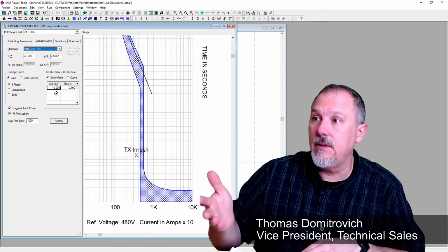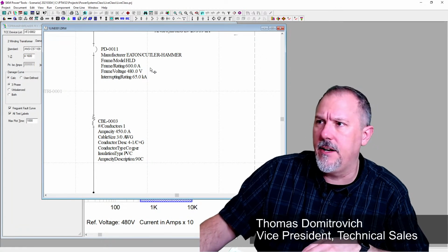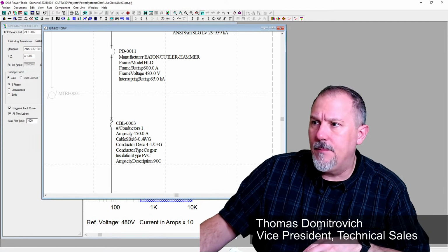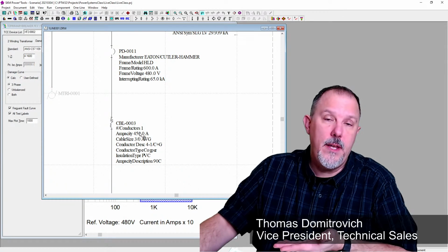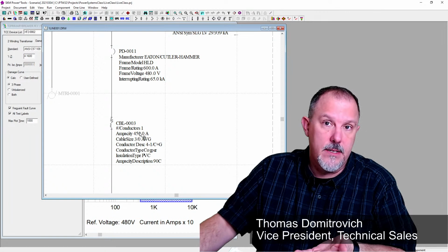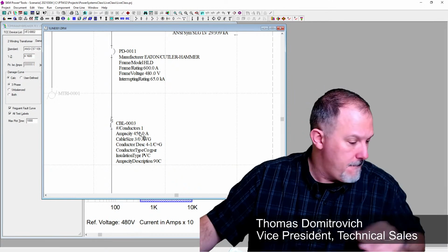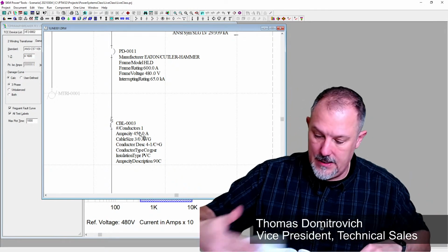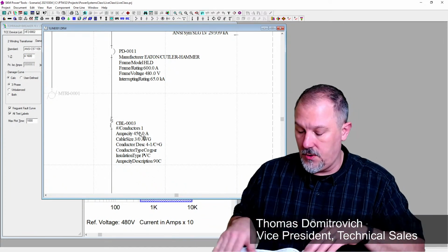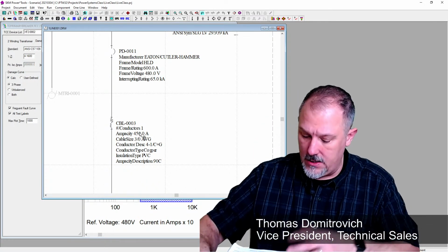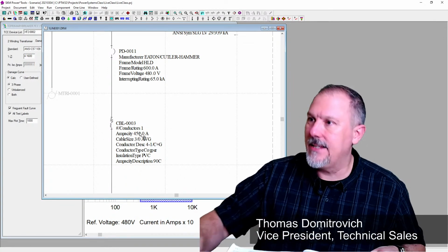So in this case, I'm at 500 amps, and that's the frame, a 600 amp frame, 500 amp trip. So I'm at 500 amps, but my ampacity of the conductors is 450. I want to be protecting the conductor at its ampacity. So I've got to do something about this conductor. That's a 3/0 conductor. If I go to 310.15, if I want 500 amps worth of conductor, what am I going to use? Shoot them out. I know we got, who do we got out there? Ryan Jackson. Ryan Jackson in the house.